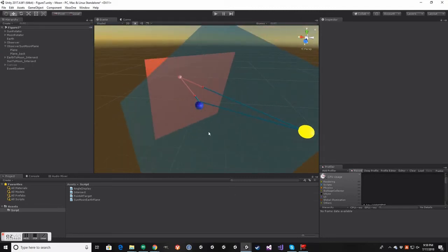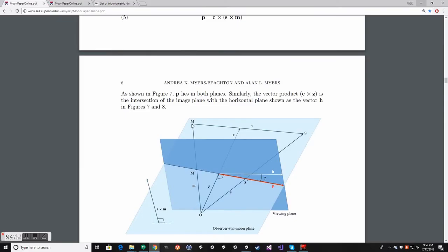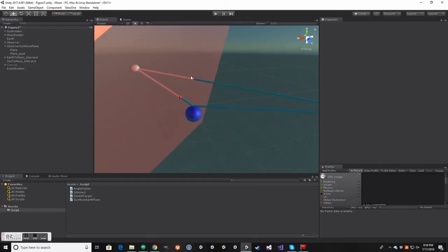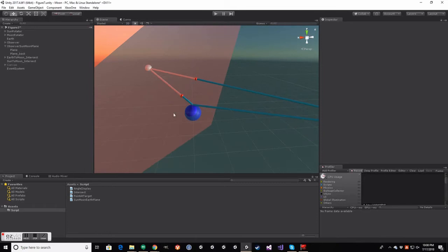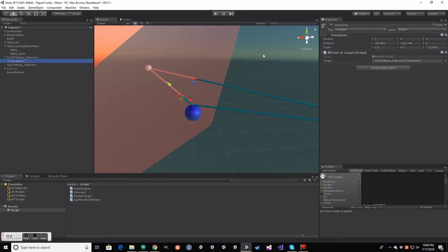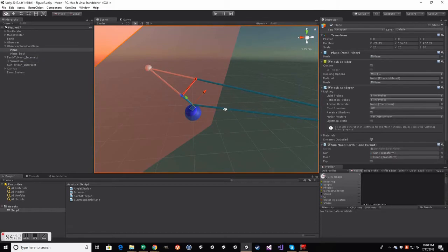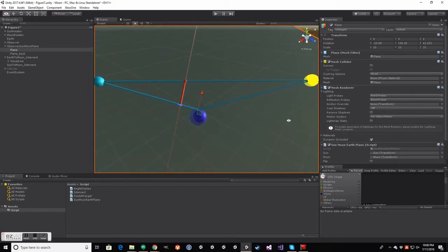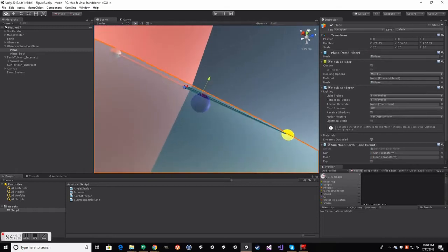I'm choosing this point. I'm going to project it back to here. You'll see that's right here. And a point a little bit further on, and we'll project that one back. Boom. So we're going to get a line segment that looks like this, but the direction of my line segment and the line segment P are going to be parallel. So I'm going to connect these two points with a line segment right here. Bada bing. Okay, this line segment represents the intersection of the view plane and the triangle.